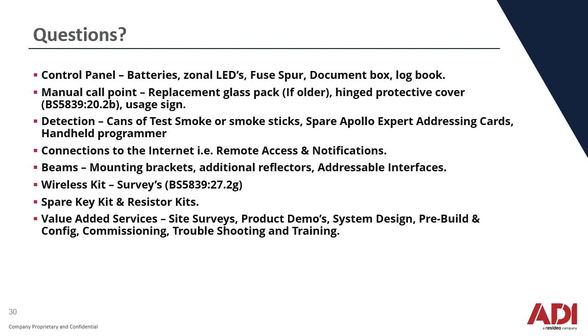Wireless equipment. Highly recommend a radio signal survey, as per BS 5839, section 27.2g. Spare key kit and resistor kits. Those small resistors are so easy to lose.